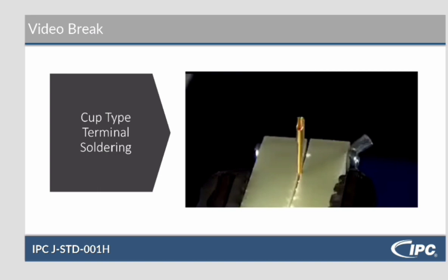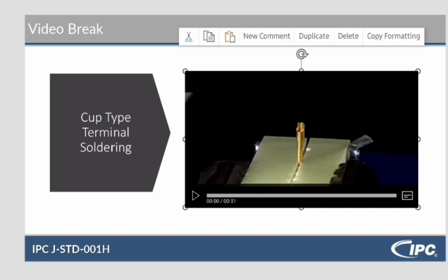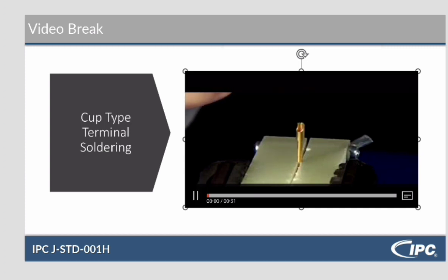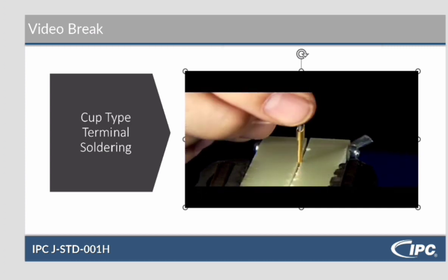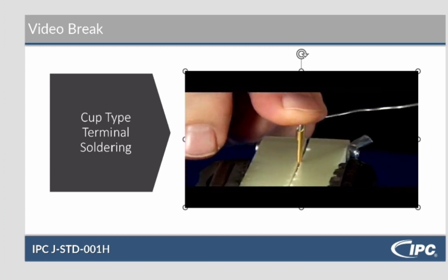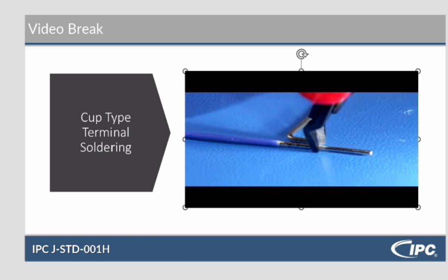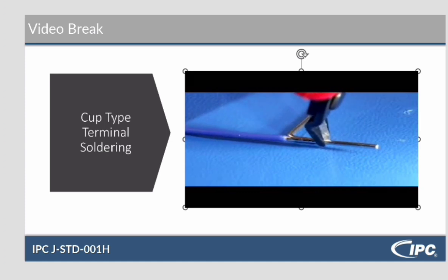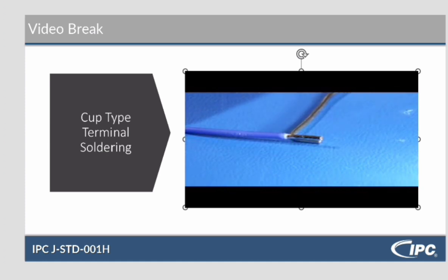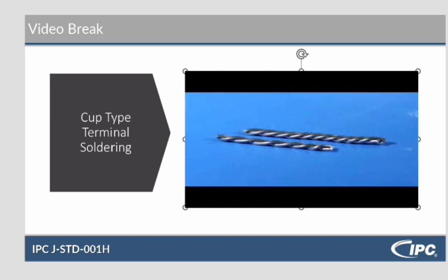What they're going to show here is a really neat trick to know exactly how long your wire needs to be. So they're putting in a piece of solder here and they're bending it over the back. And that's giving you a template. Now you know how long that wire is going to need to be. It's such a neat trick. So then you can trim your wire, your already tinned wire.